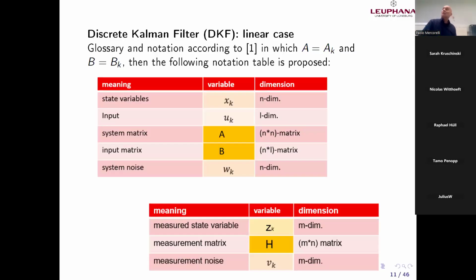This is the first slide for the introduction of the real Kalman filter. You remember the motivation of the Kalman filter. I simulated using the Luenberger observer some critical situations: noise, error in the model, error in the initial condition, three things if you like. But error in the initial conditions was not a problem for the Luenberger observer. Absolutely no problems. The problem appeared in accordance with this Luenberger observer. Of course, if you have more advancements in the Luenberger observer, we can solve also the problem of noise in the measurements.